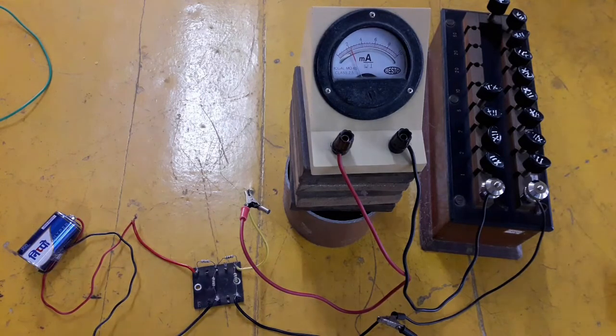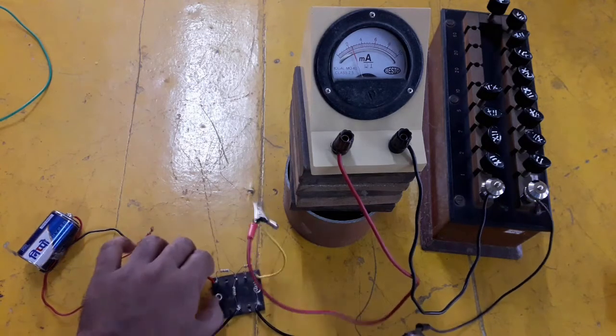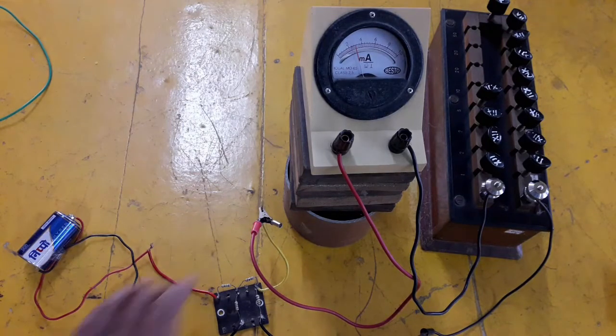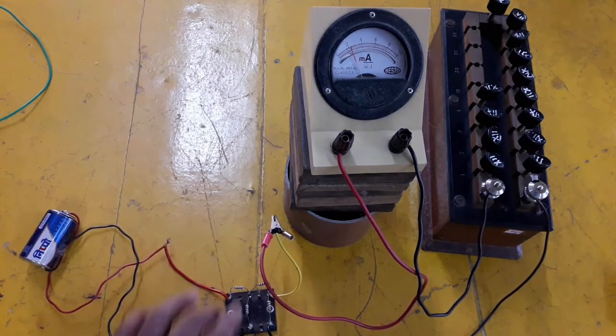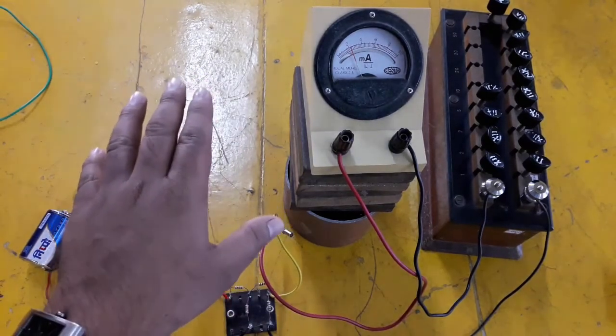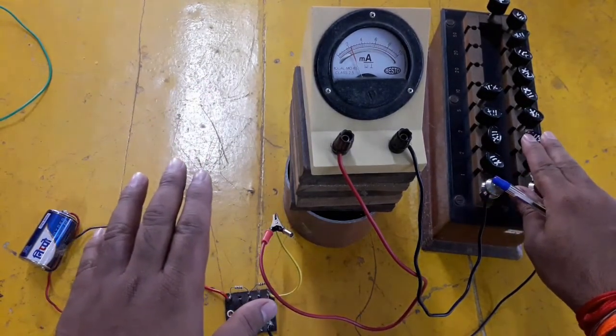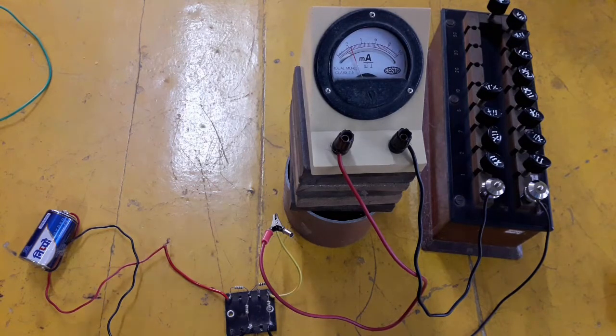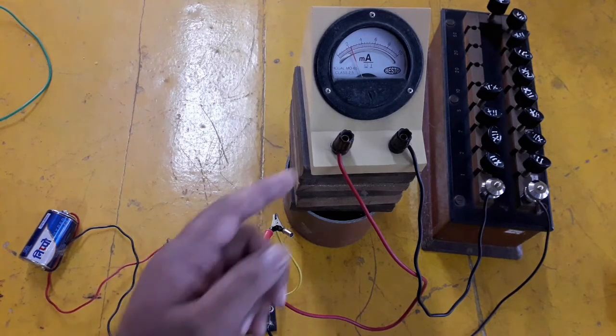Fine, so with this we have come to an end of the first part of this experiment, where we have used this circuit that is given to you, and we have found the current that we have got. In the next part we are going to replace this with Thevenin's equivalent resistance, that is RTH, of 75 ohms. So we'll remove all this, and we'll have another resistance box like this, which will be kept fixed at 75 ohms, and we'll have a voltage source which will be kept at 0.393 volts. Okay, and we will see whether we are getting similar readings in the milliammeter or not.